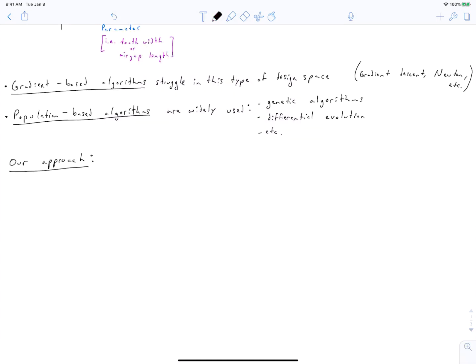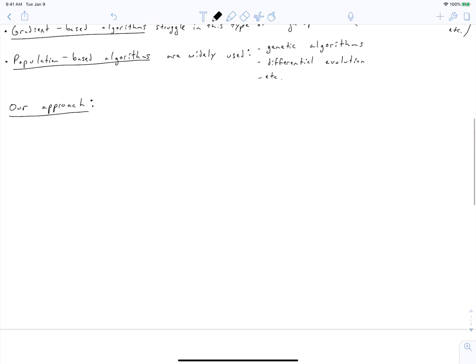And so we've talked about different concepts of optimization and multi-objective optimization. Let's now summarize the approach that we'll plan to take in our homework and design efforts in this class. Our approach is that we're going to define multiple objectives. We're doing that because we acknowledge that in AC machine design, we inherently have multiple objectives. However, we're going to limit ourselves to 3 objectives or less so that we can reasonably construct and visualize our Pareto fronts. We're going to use an optimization algorithm to search for our Pareto front.